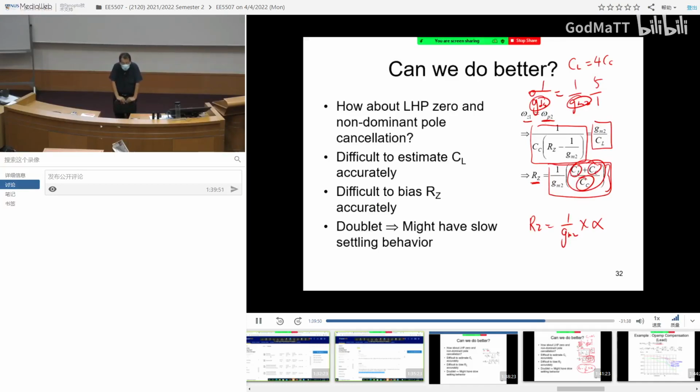In theory. In reality, you are going to have some trouble, okay? Because no matter how good you are, you cannot get exactly 100% match. There is always some mismatch. In designing capacitors, let's say you can get 1% mismatch. That is considered very good already.